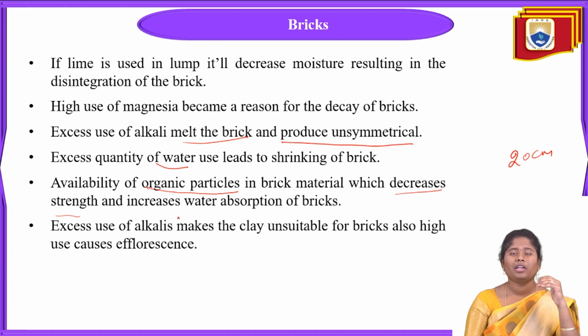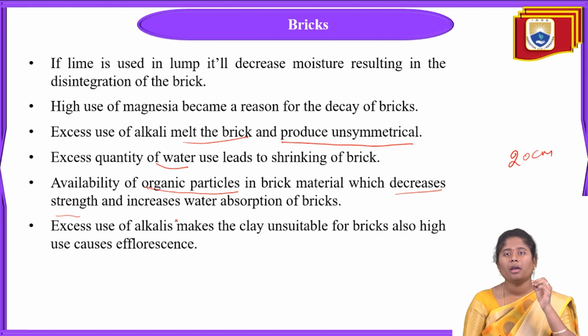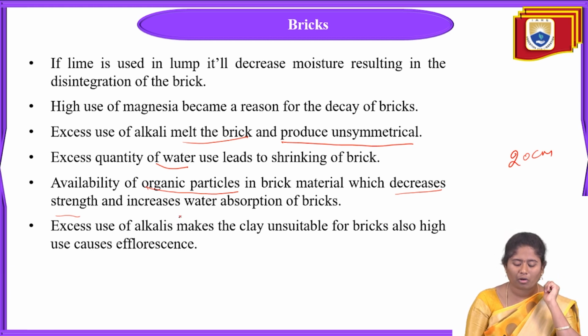If it absorbs water, it will directly cause the decay of that brick, meaning a highly brittle nature will come to the bricks. That's why we are not going to add any type of organic particles in the manufacturing of brick. Mainly it will decrease the strength and also increase the water absorption.